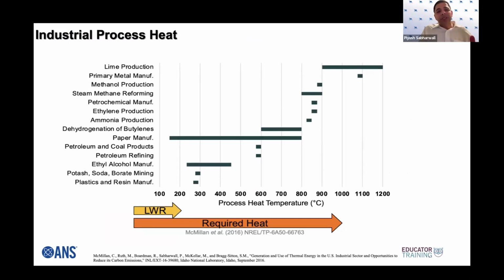The marine process requirements, like these industries, have various temperature requirements, right? So these are the industries I talked about. The 14 of those have different requirements. Current conventional reactors have outlet temperatures around 300 degrees Celsius. But with these microreactors, advanced energy systems that I talk about, SMRs, we can push that limit, right? With molten salt reactors, you're looking at around 650 to 700 degrees Celsius. With gas cooled, you can go from 750 to 900 degrees Celsius. So depending on the temperature need, you can meet these process heat requirements for these industries.